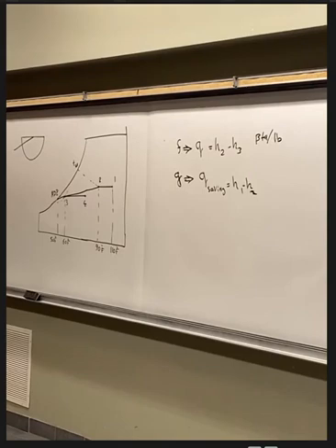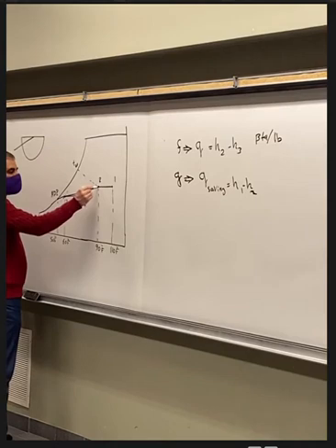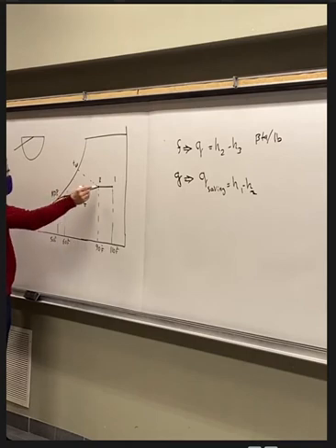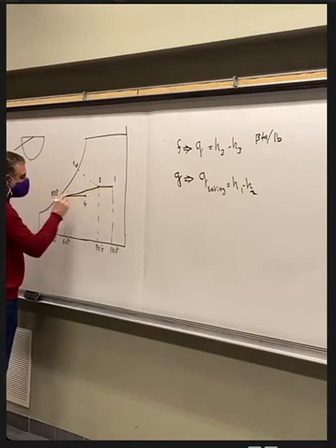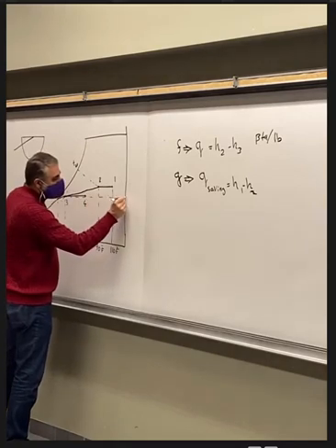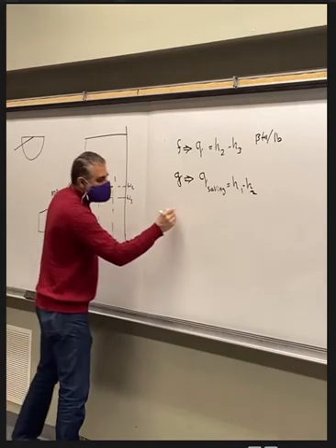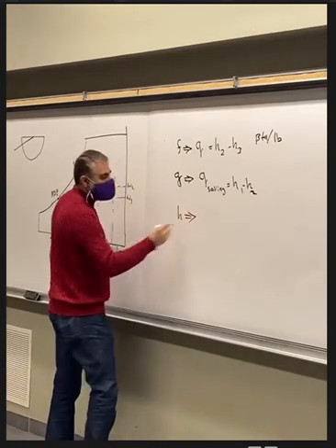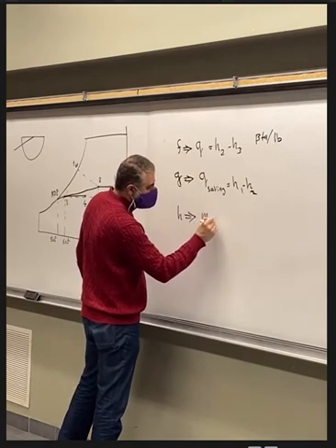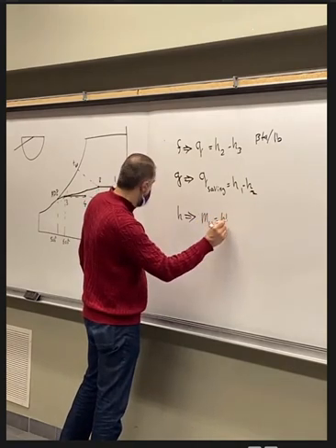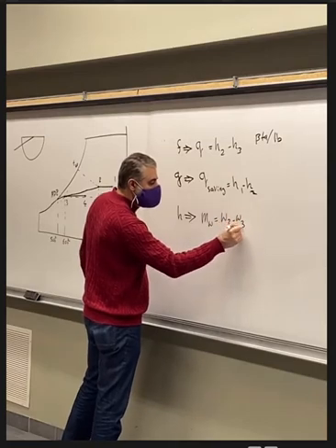What is the mass flow rate of the condensed water from the cooling coil per unit mass flow rate of dry air? Again, in this case, we have a cooling coil that changes the temperature from this point to this point, and also changes the humidity from this level to this level. So if we draw a horizontal line, that is W3, and this is W2. So the mass flow of water equals W2 minus W3.